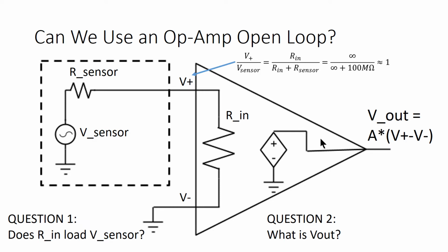Obviously, this behavior doesn't help us with our current problem. If your voltage is always equal to your power supply voltage, then you can't infer anything about V sensor. That means this op-amp configuration doesn't quite do everything we need. However, this configuration doesn't use any feedback. It's in a configuration called open loop, because the output isn't connected back to the negative input. And we observed earlier that op-amps are really good at implementing feedback loops. Maybe some feedback will help.